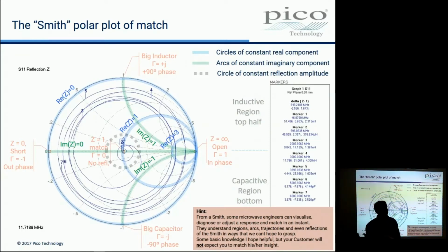What would it be? Reflections. Multiple reflections. No, it's not multiple reflections. If we had more signal coming out than we sent at it in the first place, it would be a signal source, an oscillator, or something that was already connected to another source and was outputting something. So usually your amplifiers are oscillating if you're outside this circle.